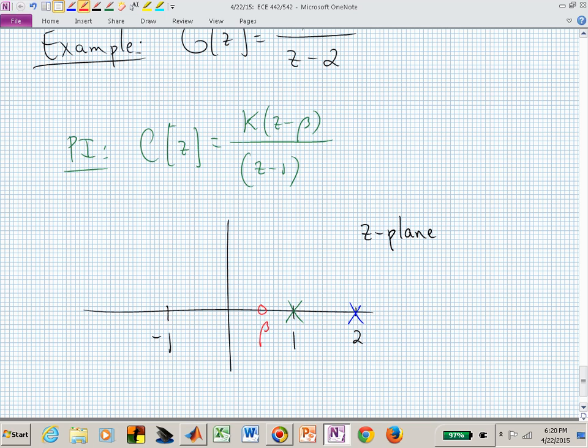Let's not concentrate on exactly where that is, but we know it's happening between those 2. There's 2 branches of the root locus between 1 and 2. Even though there's one line segment that the root locus lives on, there's 2 branches of the root locus. What's the pole zero excess? 1.